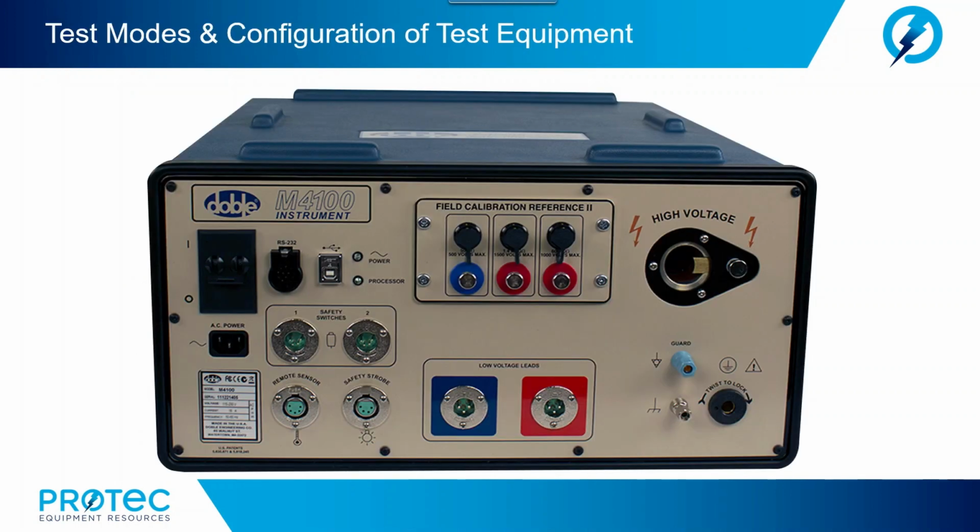All right, now let's start talking about test modes and configurations of the test equipment when we perform power factor or dissipation factor tests. To help us in understanding the operation of the test set, it is important to consider the relative positions of the test set's power source, for example, the 10,000 volt winding of the set's high voltage transformer, the measuring circuit, and the specimen being tested with respect to the test ground and the low voltage measurement leads.